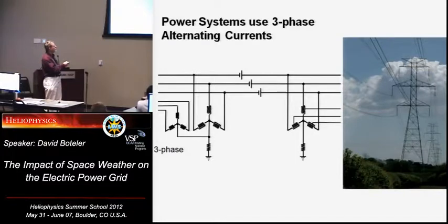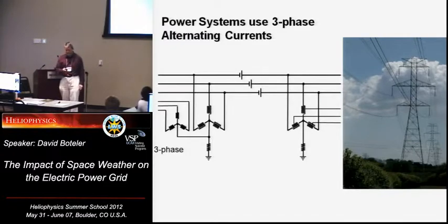In practice, they connect this to ground, because there's two things that can happen. One, you can get a lightning strike on one of the wires, so they want a path to conduct that current away to ground. And the other thing is, if one of the phases goes out, because there's a break in the line or something, then suddenly the three phases don't add up to 0 here. You've got an enormous amount of current coming into that neutral point, and you've got to dump that somewhere. So normally there's no current flowing in there, but that's maintained as a key safety feature of the power system.